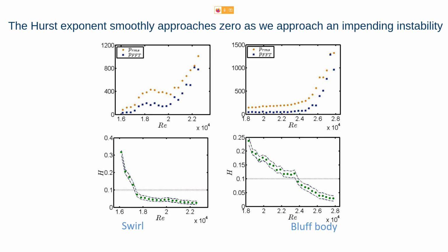So people use this as an early warning signal, where they try to find these values pretty early before the system transits, and get the warning of an impending tipping to thermoacoustic instability. And we can see from these two figures clearly that when the system is near this region itself, you are getting a warning that you are going to some kind of thermoacoustic instability, so be aware. So you can say that you are getting some alarm over here, in these two regions.